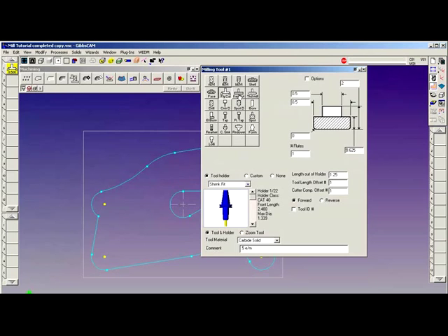For keyways, Woodruff keys, keyway cutters for undercutting, you can define a keyway cutter as the overall length, shank diameter, cutter diameter, and in this case, we have a provision for an upper radius and a lower radius. If we were using a round cutter, say for example, to generate O-ring grooves, make the upper and lower radius the same, and then we'd add the two radii together to get the thickness of the cut. That would give us an O-ring cutter or a keyway cutter with a radius. Number of flutes, and again, length of cut or thickness of the cutter.